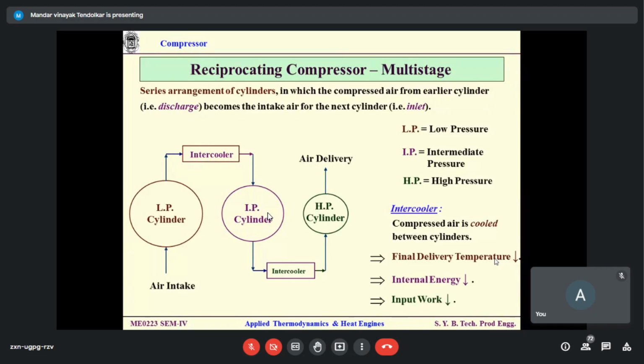What I want as the final one. If I do not have any intercooler, let's say this is 27 degrees. After compression, 100 degrees. Then second compression, 200 degrees. Over here, 300 degrees. I do not want that because that is direct exergy loss. So what I do: 27, let's say 100. Bring it back to 27, 100. Bring it back to 27, 100. Are you getting this?